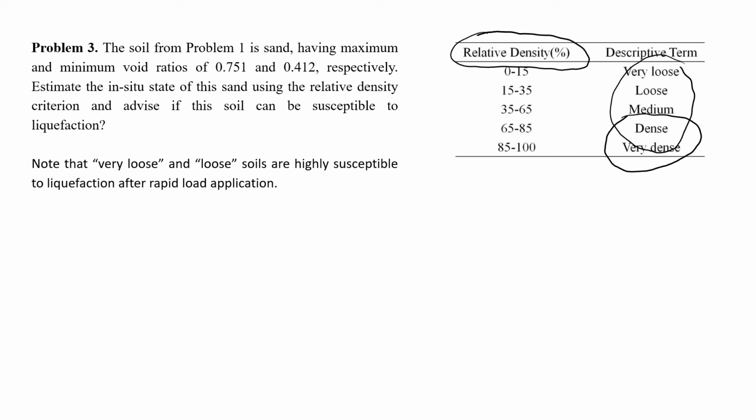Let's see how we can use relative density, and we can actually apply it to solve some real-life problems related to liquefaction. So we have a soil sample, and we examined it, and we got the maximum and minimum void ratios.